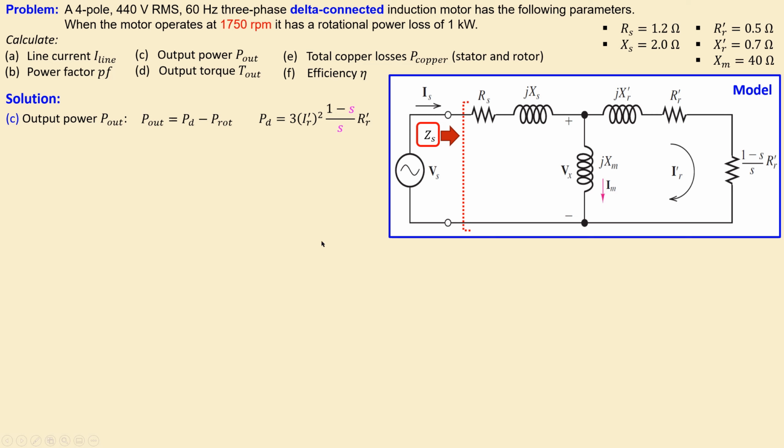Before we move on with that one, we need to of course use the per phase current for this. So we have a current divider rule. What we want is the current here, which will split in 2 branches, but we know this, and we can now use the current divider rule, which is given by this expression. So this current, which is flowing in this branch, is equal to the other impedance, which is shown here, divided by the total impedance in this branch together, which is shown here. And again, I have taken these 2 resistors, R prime, and also the load together, which is this expression, and you multiply this by the source of this node, which is just IS.